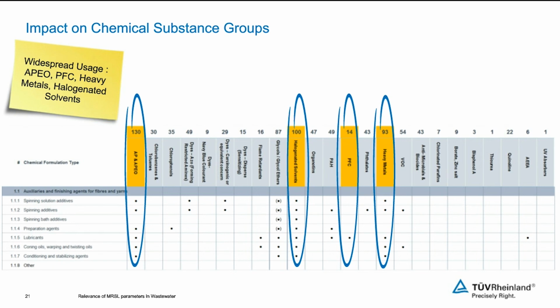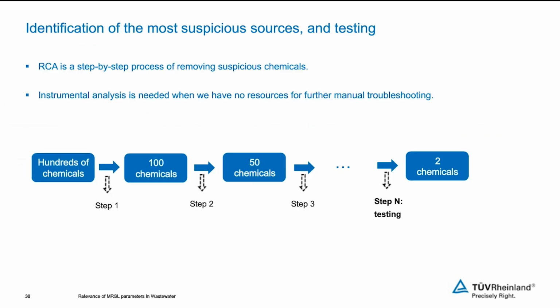How long does it take to do the RCA? I think it depends. If the factory has a good chemical management system and all necessary documents are available, we only need to spend 1 or 2 days for the on-site document review, and 1 or 2 days for the on-site plant tour to check if any contamination or other chemicals are used in the factory, and then wait for the testing reports of the most suspected chemicals for around 10 working days. Once the root cause is addressed, the factory can then start the substitution.